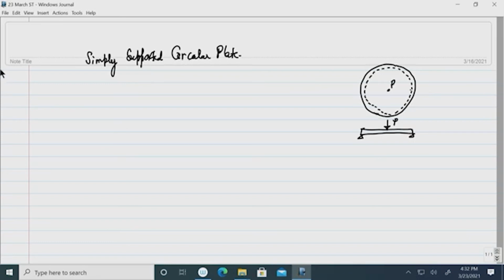The equation of the plate deflection is known, we can take the third order equation, we can take the fourth order equation. Okay. Now, here we shall take a slice around the load and consider the equilibrium of the slice. Okay. So, load is acting here P, and we have the shearing force that is acting around the slice of magnitude q_r per unit length.